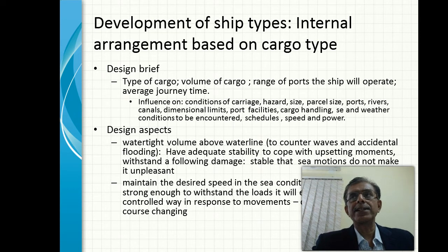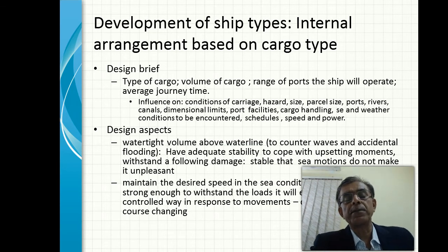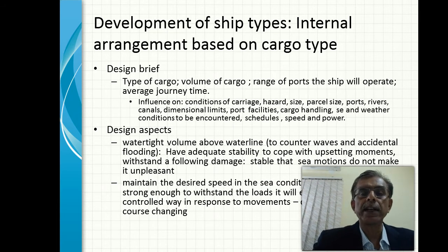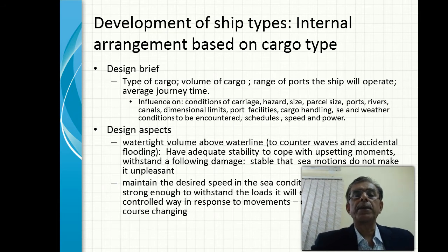Fundamentally, a naval architect starts from the very design concept, which essentially is a brief from the owner on what is the purpose of the ship and what is the cargo this has to carry, what are the range of ports it has to operate, what is the journey type. Fundamental design is part of a pre-contract phase, which is a brief which comes to the naval architect who will have to produce the contract phase from a shipbuilder's perspective. Or if he is working for a shipping company, he prepares the pre-contract documents.